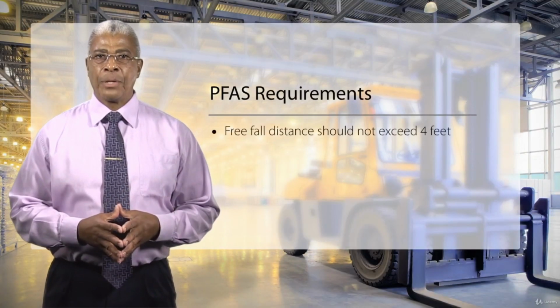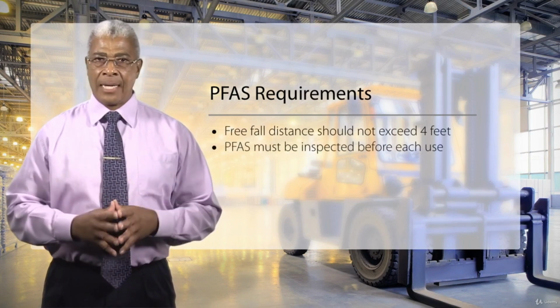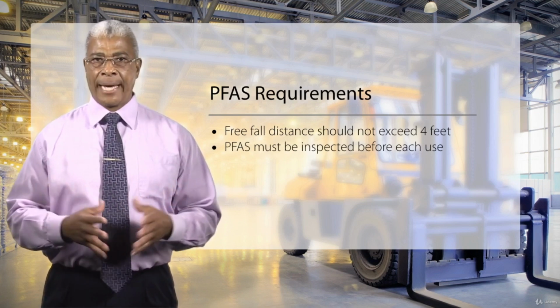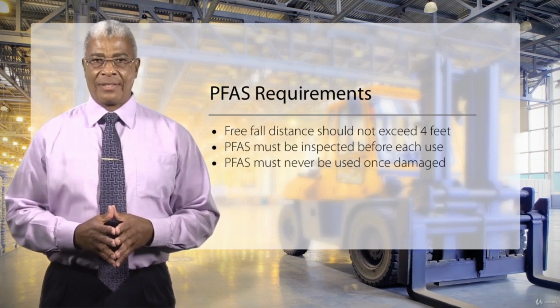After a fall, there should be provisions for a very quick rescue. In addition, every PFAS must be inspected before each use. No PFAS may be used until it has been inspected by a competent person. Finally, a PFAS must never be used once damaged.